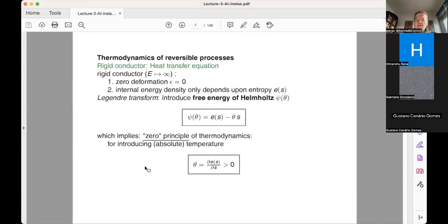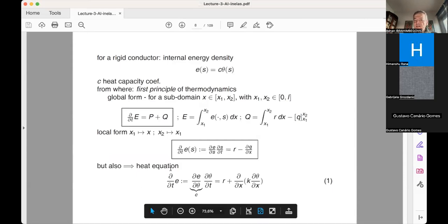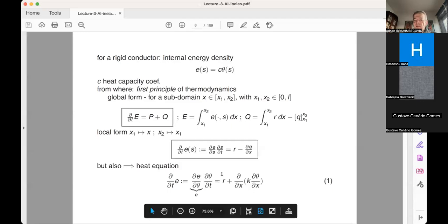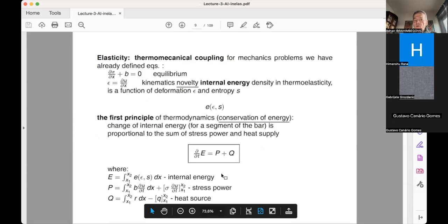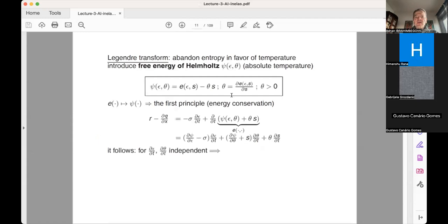So basically, we introduced thermodynamics as the study of heat transfer, and I also showed you the time integration schemes that are applied to first-principle thermodynamics for the heat transfer part, which simply amounts to the very well-known heat equation. Basically, it says that internal energy is changed by heating. Then you go to the more general framework of thermomechanics, and the internal energy is changed not only by heating, but also by something called stress power, the product between the stress and the strain rate.